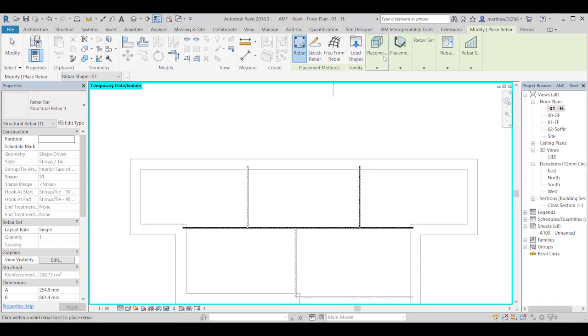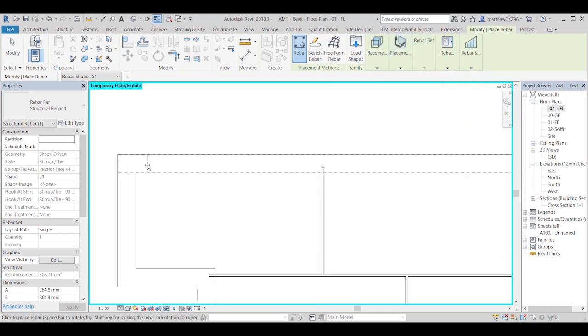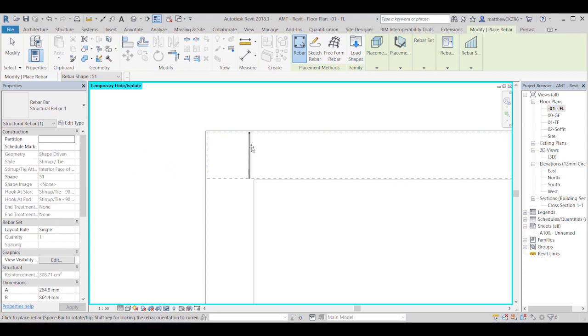So if we go to the placement and we click on near cover reference, placement perpendicular to cover, then our rebar will start setting in. If you toggle around, you'll notice that it goes perpendicular to the nearest cover. But we want it there, as in the links go across, all the way across here, and in this motion. Hard to explain, but hopefully you're on the same page I am. So if we just go click, that's our bar.